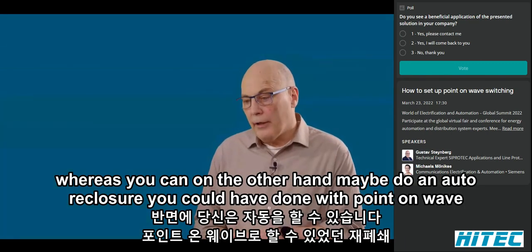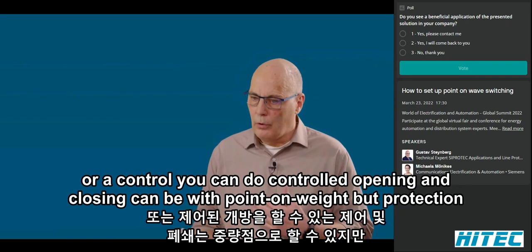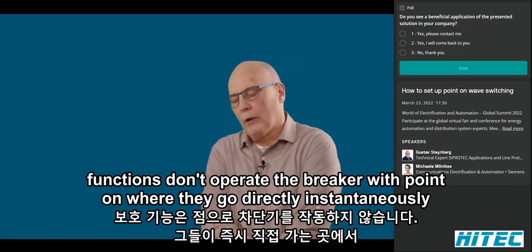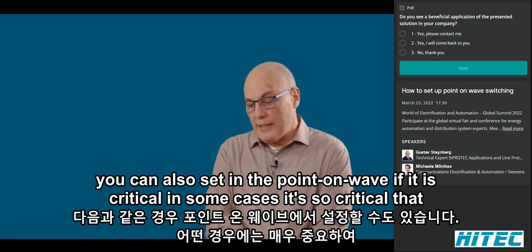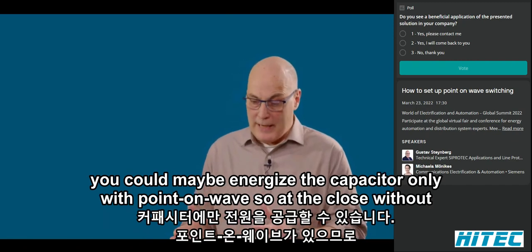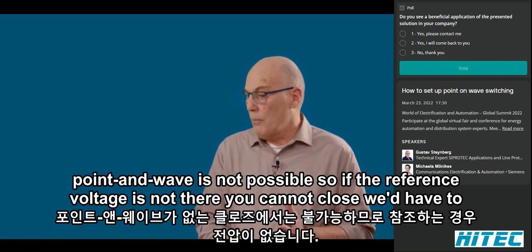Whereas you can, on the other hand, maybe do an auto reclosure you could have done with point-on-wave, or a control. You can do controlled opening and closing with point-on-wave. But protection functions don't operate the breaker with point-on-wave. They go directly, instantaneously. You can also set in the point-on-wave, if it is critical, in some cases it's so critical that you could maybe energize a capacitor only with point-on-wave. So a close without point-on-wave is not possible.